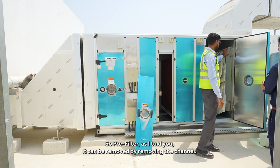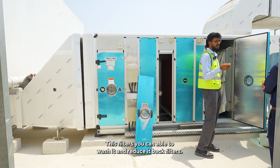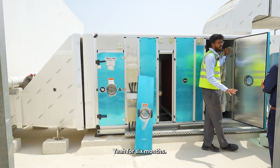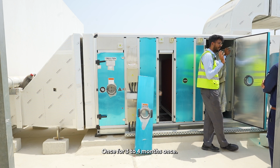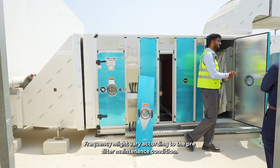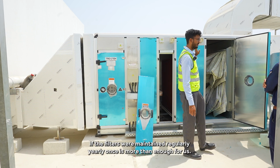So the pre-filter, as I told you, can be removed by removing the channel. These pre-filters you can wash and reuse. Back filters need to be replaced. For AHU, 6 months once, for FAHU 3 to 4 months once. Frequency might vary according to the pre-filter maintenance condition. Cooling coil, if the filters are maintained regularly, yearly once is more than enough for us.